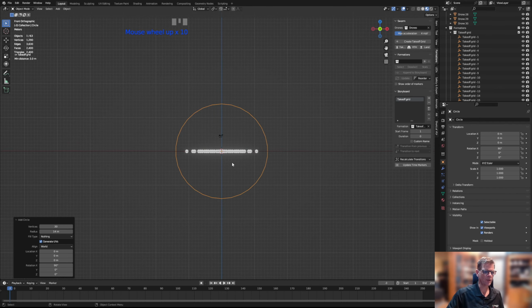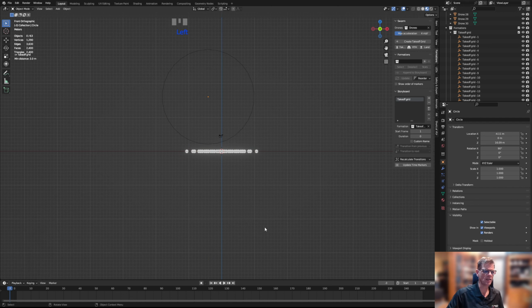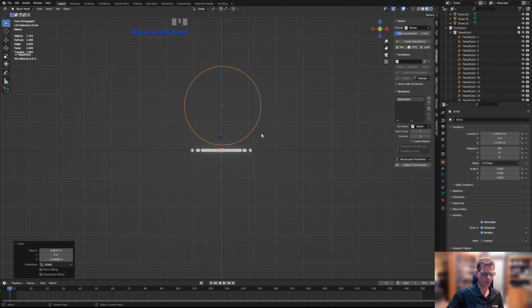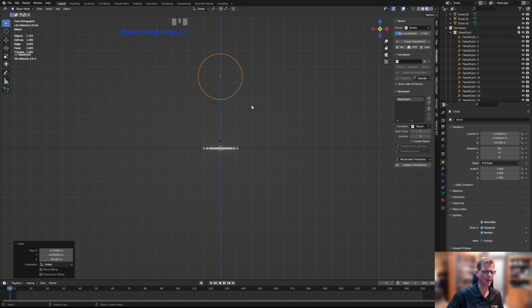We don't want to go below ground, so in these locations here you can drag the sliders left and right, up and down. As soon as you hit a mouse key, these options all go away, and now you have to revert to normal methods. So let's make the circle take off to right above. Let's actually be careful. Let's say that's the height that our lights are at, so that when we're moving over, we're at least above the lights. And we're now ready to assign these drones for the first formation to the vertices.